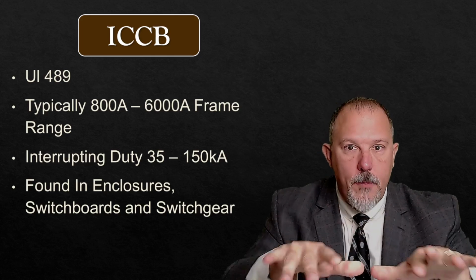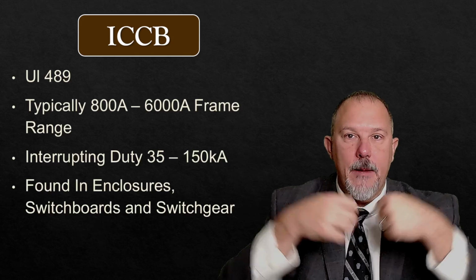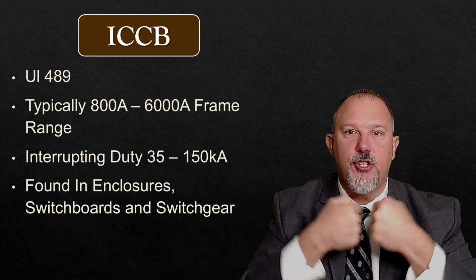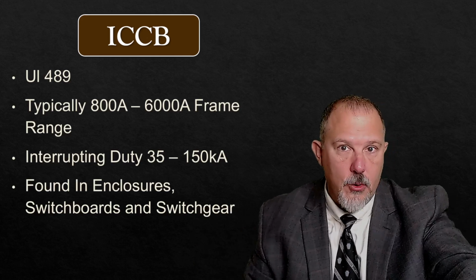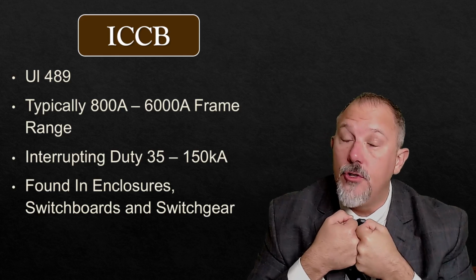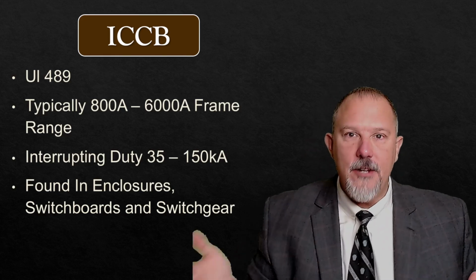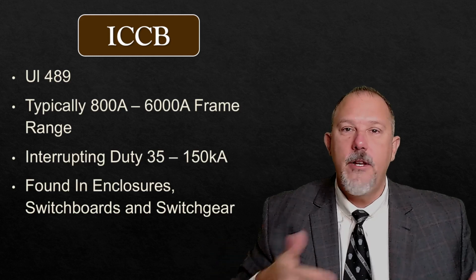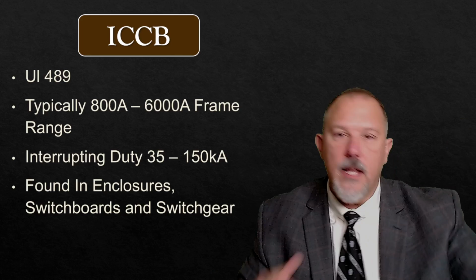Why would I want to do that? I want my little puppies downstream to open and clear faults so that I maintain a reliable power distribution system to everybody else. So you isolate your portion of the system while I hold my contacts closed and let you do your job. That's a good manager, right? It's a good leader. Think about leadership.